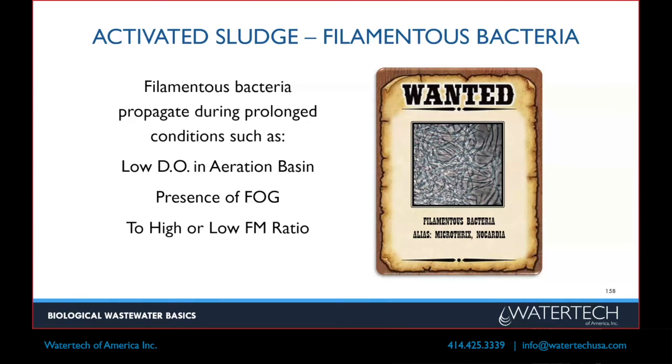The other is filamentous bacteria. There are lots of different things that can cause filamentous bacteria within a biological system. Low DO, presence of fats, oils, and grease, that F-to-M ratio being too high or too low, just a lot of different things. But you can kind of tell from the picture, they look like spaghetti.